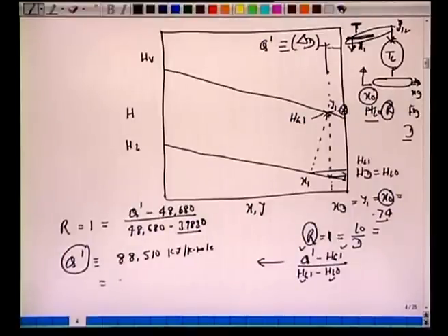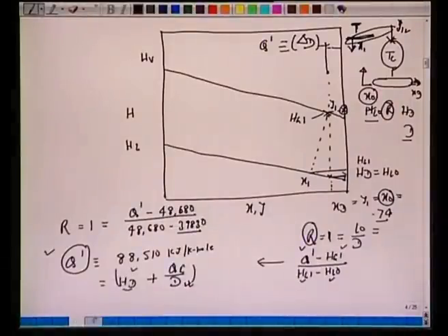And this Q dash prime, if you recall, is HD, enthalpy of this saturated liquid product here, plus QC over D. So that's what we say, this hypothetical liquid which carries an energy of HD plus QC by D. So Q dash is known, HD is known, D is known. Okay, D we have to evaluate right now to calculate this QC. So now let's make enthalpy balance or total balance. So we have F as D plus W.